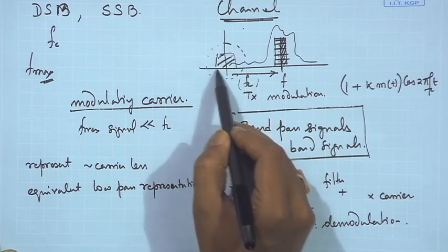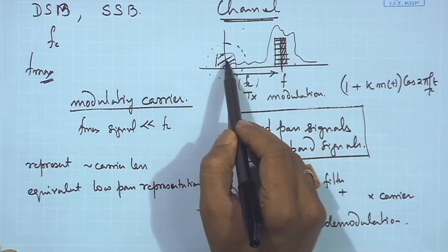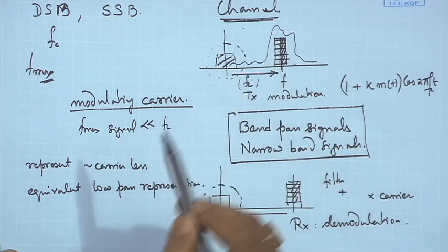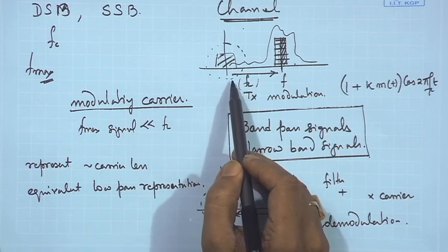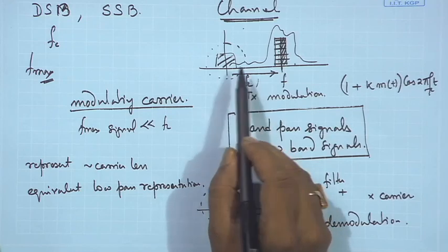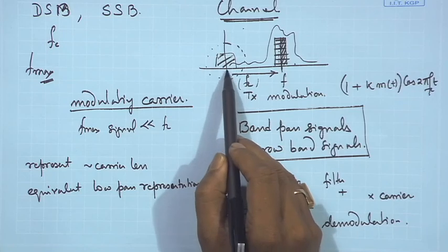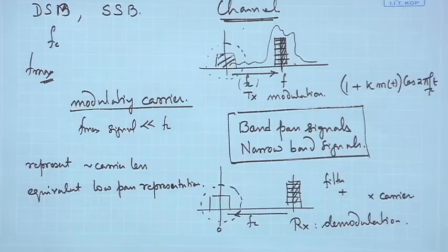So, we would like to represent the signal in the baseband, as well as we would also like to have the channel's representation in baseband, which will be clear in the next lecture. So, that we can study the entire thing in baseband without affecting the performance of our study. And if we know this carrier frequency, then we can translate all the studies that we do in baseband to the corresponding effects of the passband. Or in other words, what we are going to establish soon is the relationship between the baseband or the low pass equivalent signal and that of the passband signal, so that we can do the studies in the equivalent low pass form. Thank you.